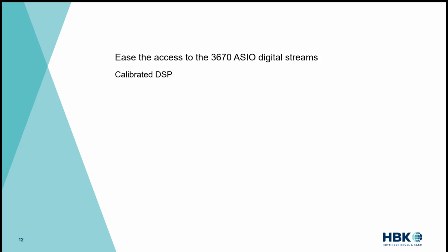It is rather simple to transform a complex data set into magnitude and phase, but typically to get an FFT without leakage, you need to pre-process the time block with a special window like Hanning or Hamming before you do the FFT, and that will affect the magnitude of your spectrum. So when you use an FFT processing function, you need to make sure you don't have any leakage, and your code will provide a corrected magnitude. This is what the electroacoustic engine will do for you, and this is what I mean by calibrated DSP.